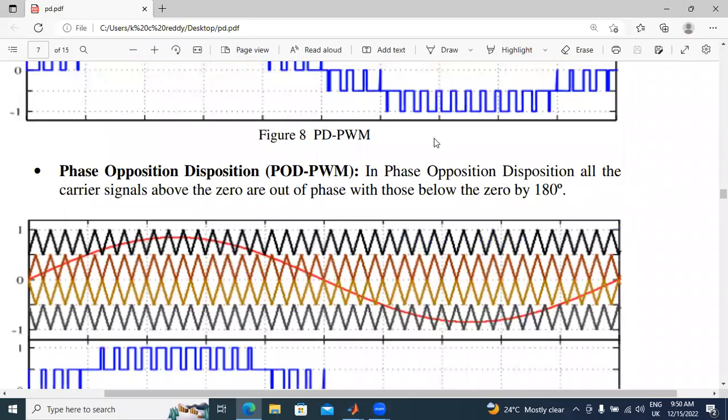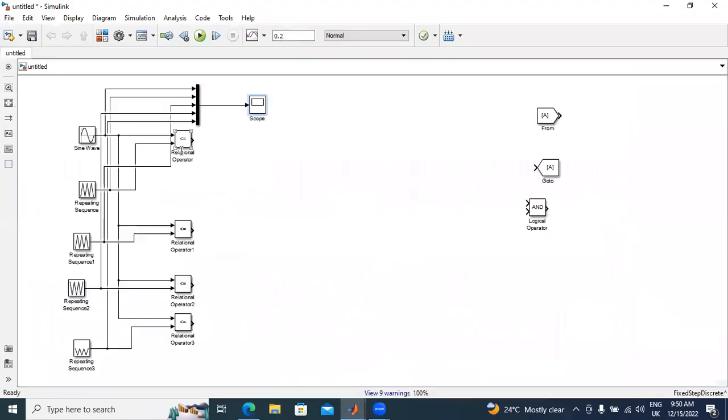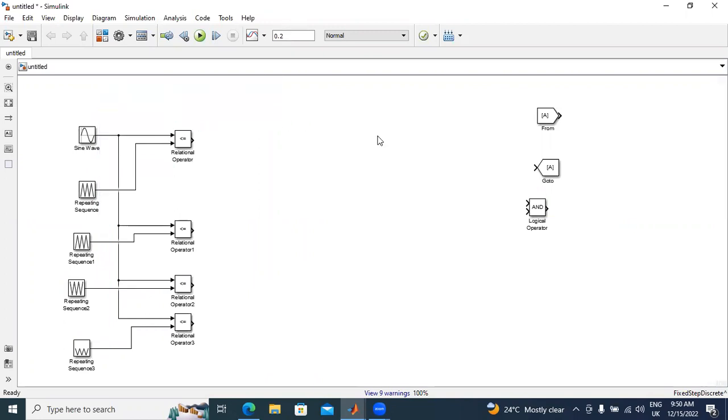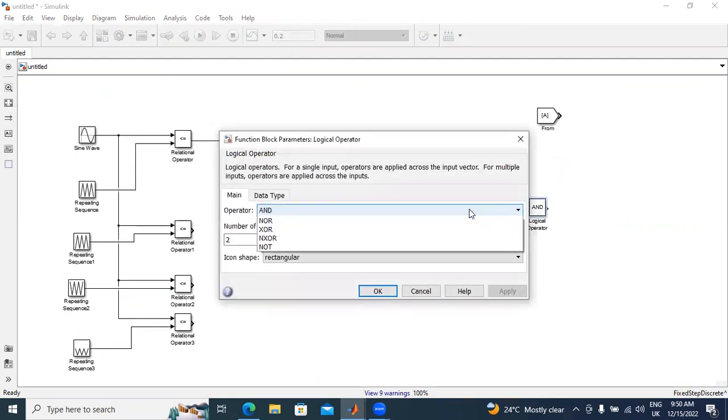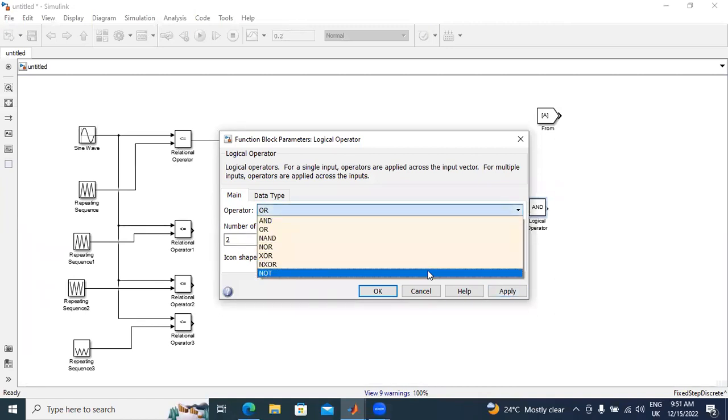Now I will connect this PWM signal by using this control scheme. I will connect a 5-level cascaded HBridge inverter. Now I will design the circuit. Before designing the circuit, I will apply the pulses here. I will generate 8 pulses. I will take here a NOT gate.